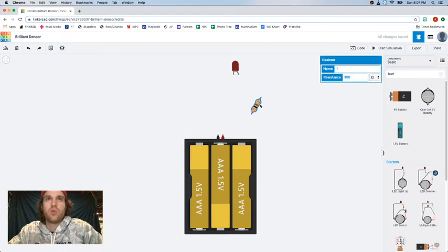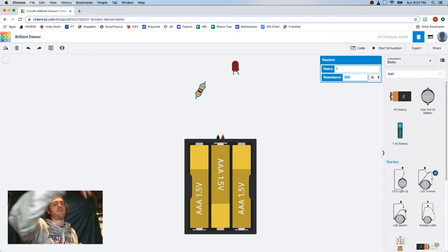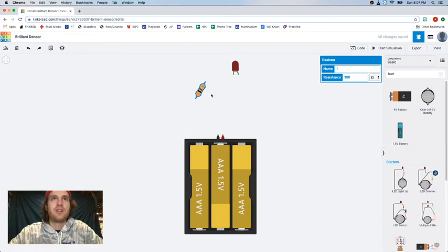Another question is, which side of the circuit does the resistor go on, the positive side or the negative side? It actually doesn't matter, okay? It doesn't matter which side, because wherever that resistor is, it's a complete circle, right? So it's going to slow the electricity no matter where it is, and all the electrons are bunched up almost like a traffic jam moving through. So the amperage will be the same if you put it on this side or on that side.